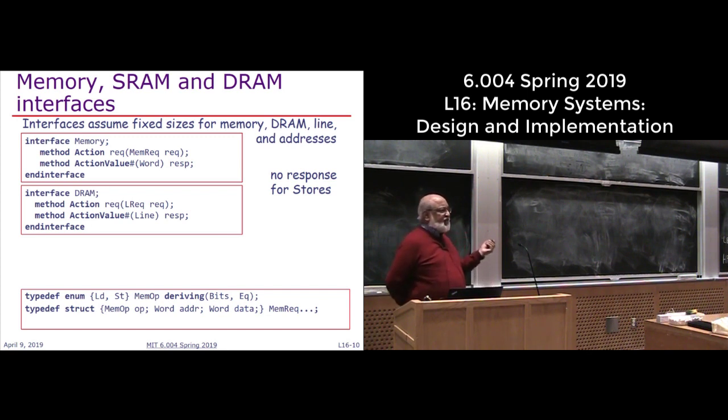Because you can have different interfaces to memory where you are told the answer will arrive 4 cycles from now, and if you don't catch it at that time, it will be gone. I don't want to deal with that kind of interface. We'll hide those kinds of timing issues. We will assume whenever it's available, it will stay there until I pick it up. Good. All right. So it looks exactly like the memory interface.